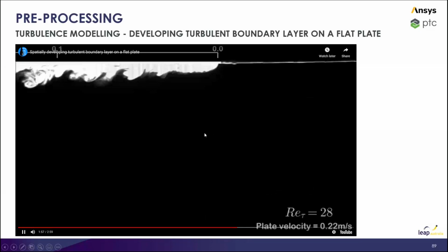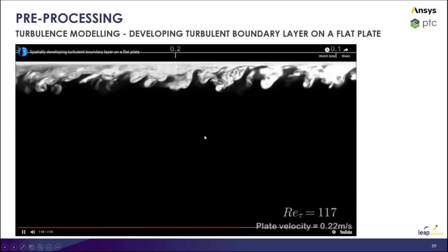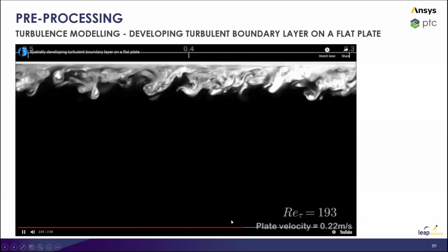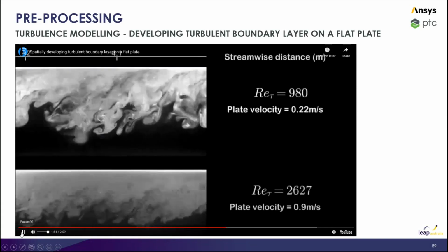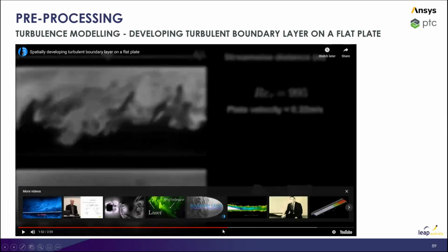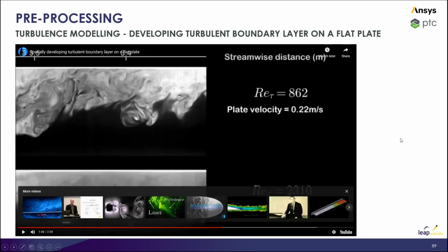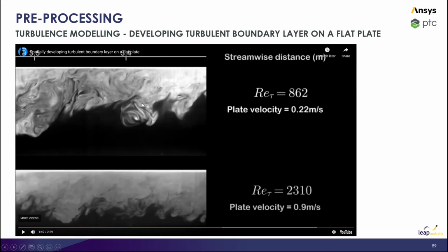And so we remember that the higher velocity will be a higher Reynolds number, and so that one was probably a higher level of turbulence, you can see here. Now, a couple of important properties about turbulence that they try and capture when we're doing turbulence models is that turbulence has a length scale. Okay, and you can kind of see that here.